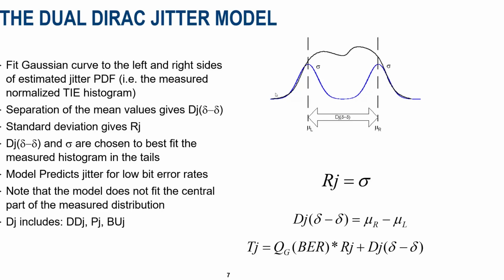There's a lot of limitations to this methodology. One of the most difficult is how do you fit the measured data to the model? Well, the fitting is kind of a black art. There's a lot of detail in there that's not talked about too much, but it does definitely have a fair amount of error in that fit that can result in errors in the overall jitter measurement.